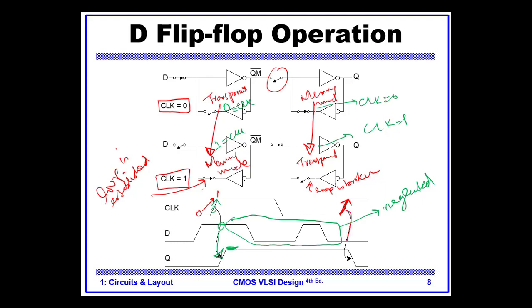It picks up the input, transfers it to the output after some delay, and the state changes. You see there is nothing inside this circuit which can detect the positive or negative edges, but the combination of these two latches gives you a behavior which feels like it can detect an edge.